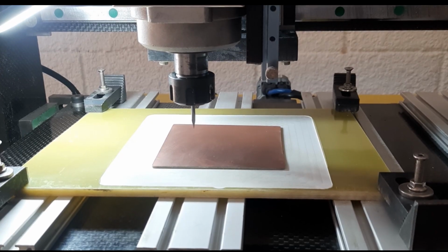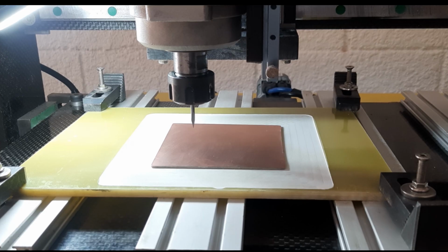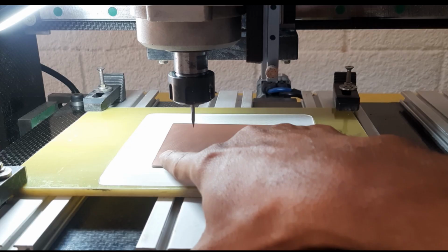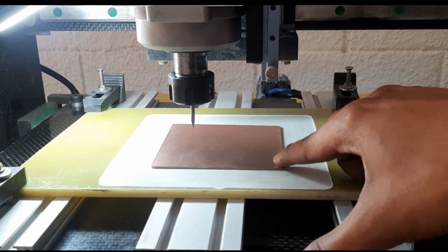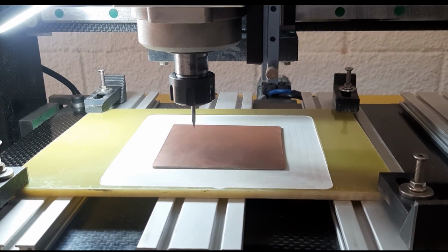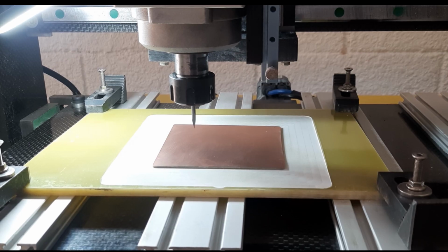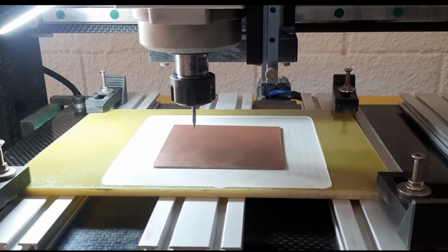I've positioned the bit to the correct X and Y0, taking into consideration that we also have to put 4 alignment holes later. And while finding the Z0, you can get the bit probably 0.1 mm above the board to start off with, and then incrementally lower it through trial and error.